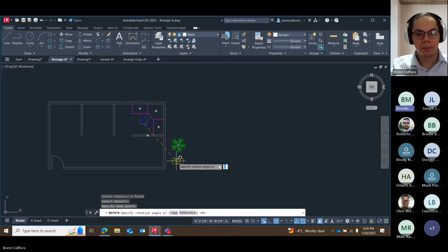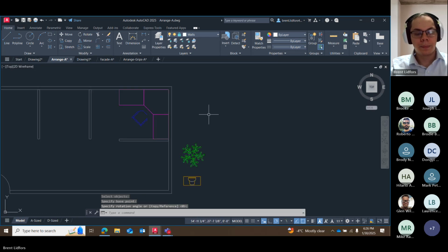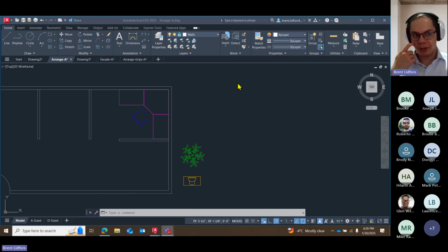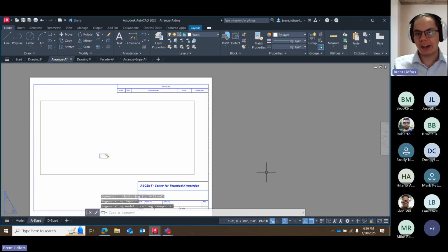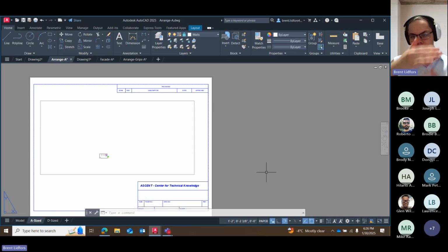Why is it so difficult to convert your file into a PDF? Few reasons. AutoCAD likes being very specific with its layouts, so it wants page setup to be very exact. Just because when you go to make physical blueprints, they have to be pretty precise in terms of their design and everything when it gets printed out. So it's not like your standard Word document where you're probably printing on A4 every time. When you're printing blueprints, the size of paper could vary quite a bit.